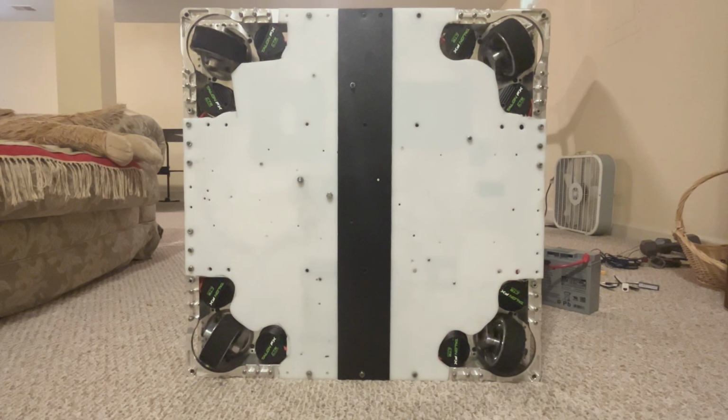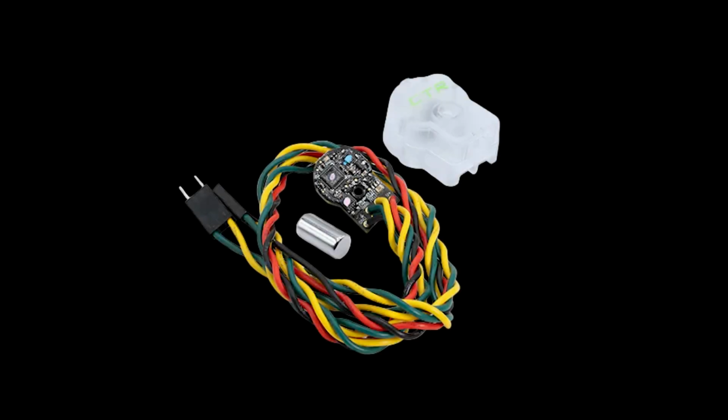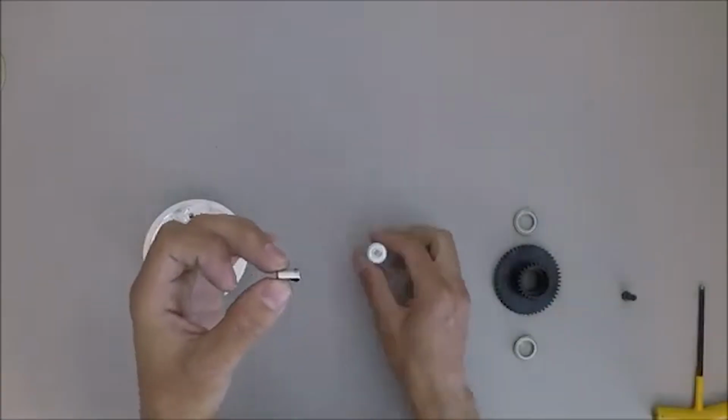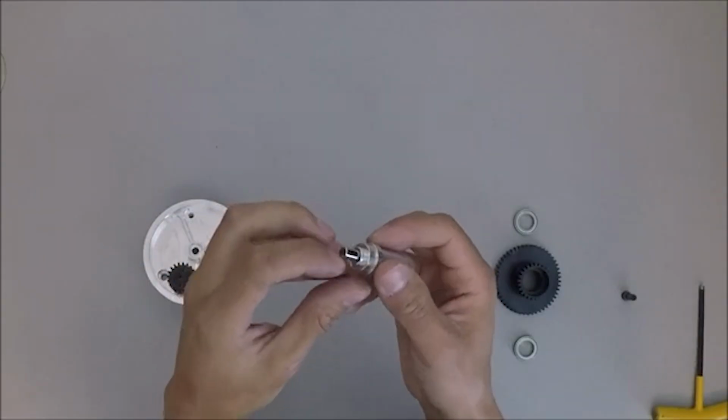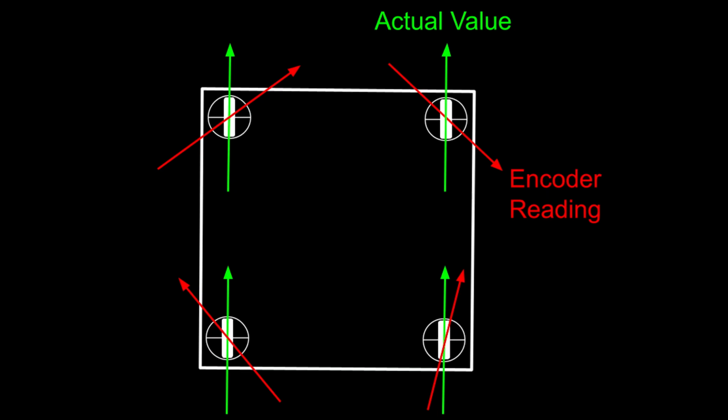It is the fault of how the absolute encoders were mounted. For popular absolute encoders, such as CAN coders, it is very difficult to figure out the orientation of the magnet because it has no markings, and it is simpler to assemble it randomly and correct it within our code. So to get our Swerve code to work correctly, we'll need to add offsets for all of the wheels. So let's figure out the offset values.